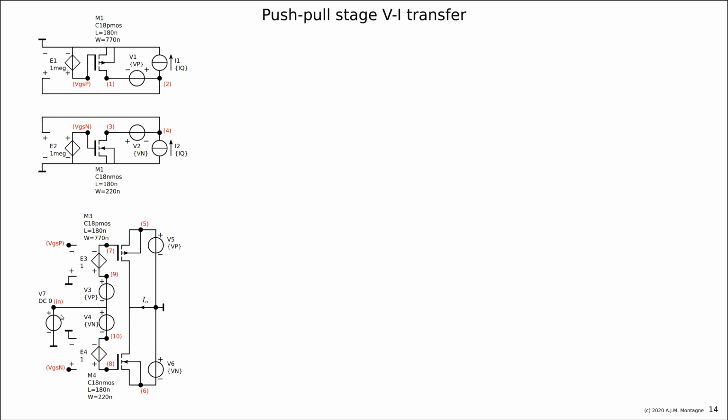and I can connect a DC voltage there to sweep the voltage at the input and measure the short circuit current exactly as I did in the differential pair. But now I have one current, so the current of one minus the current of the other is just the current in this node. And in the LT-SPICE, you put there a voltage source and you measure the current through it, and we can plot the voltage to current relation of this system, of this stage.